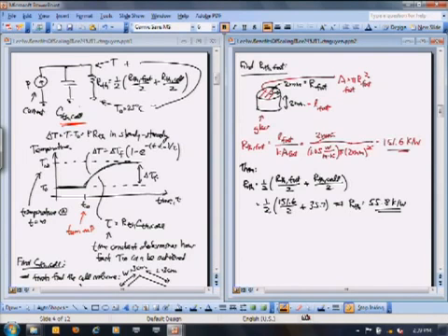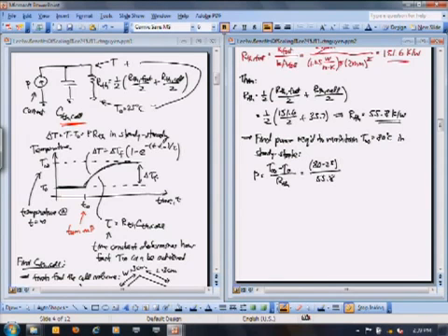Okay, so the first thing let's do, let's find the power required to maintain that atomic clock temperature. I'll call T infinity equal to 80 degrees C in steady state operation of this clock. And so from the equation that I put down before, just looking at the voltage difference or the temperature difference in this case, so T infinity minus T naught divided by the thermal resistance in this case. So just like any simple EE problem, I have these numbers in. That ends up being 0.99 watts, which to me is 1 watt. Okay, so to keep this cell at 80 degrees C requires 1 watt of power.